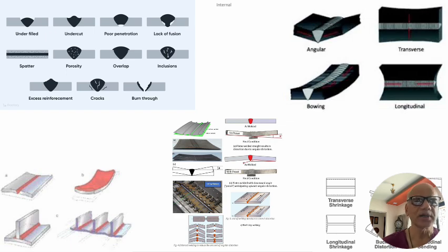And you can see from the figure itself, and this is what the reality also many times we see. The welders who are not able to see the profile of the weld through their screen, they'll end up with this, or the parameters are bad and they're using the excessive arc length. This is what will happen. It will spread, it will have lot of deposition only in the center portion, but the rest of the area is getting melted and flown, and that's where the width goes up. So reduce your arc length, reduce your arc voltage, use proper current. I'm not saying that use low current or a medium current. Even if it is within the range, you should be able to do it.